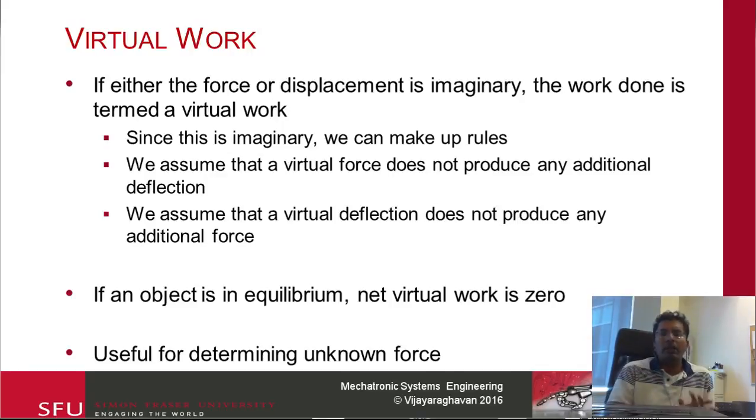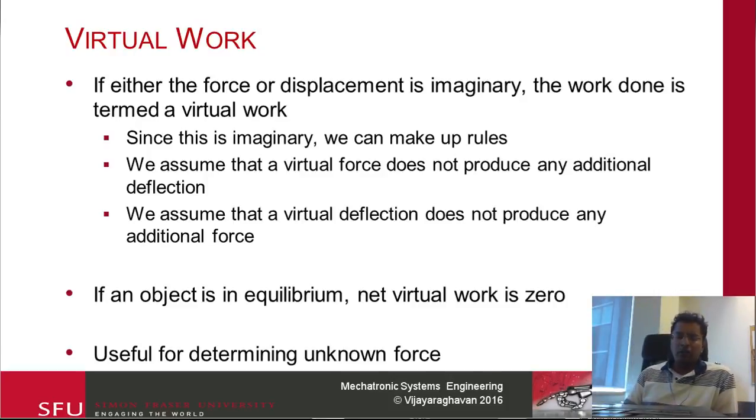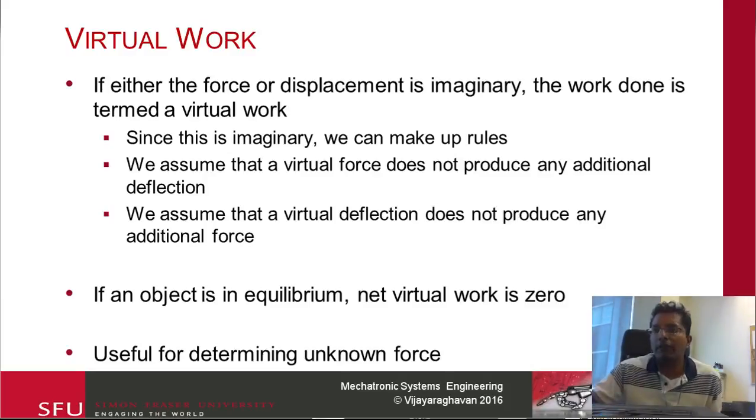So we assume the rest of the equations are valid. If the system is in equilibrium, forces need to balance. If the system is connected and you're doing a virtual displacement, all the displacements, or the distances it moves, need to match up properly. If we apply a virtual force, it's useful for determining an actual displacement. If we apply a virtual displacement, it's useful to calculate the unknown force. Previously we applied an actual 1 Newton force, but it's not needed. We can make it a virtual force and make our life a little bit easier.